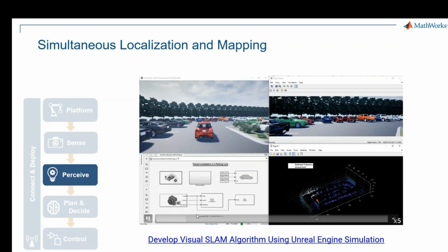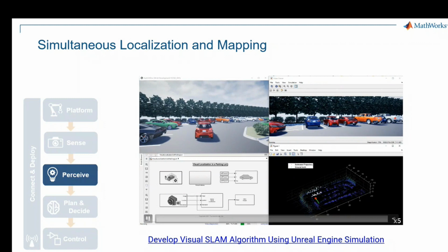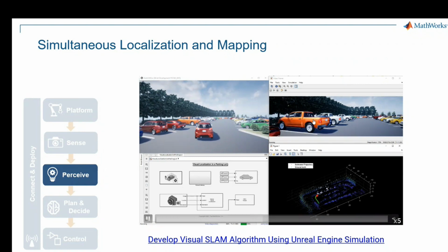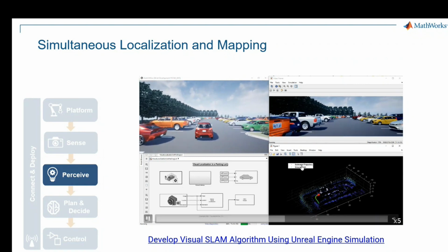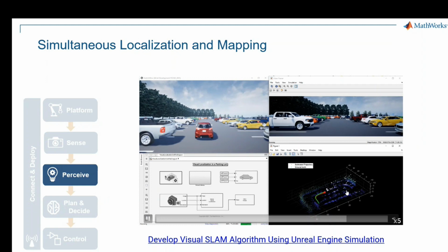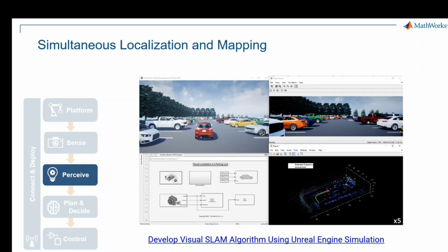And maybe it's too small to see, but the idea of this algorithm is that at each frame, it's going to detect features on it that are going to be added to this map. And these features are going to be tracked over time. The tracking of it is going to create an optimization algorithm for the localization, and also keeping them is going to create the map as you see below. And once this vehicle comes back to a position that is already known, in the SLAM algorithm, there is something called loop closure. That is an optimization algorithm that lets you close the loop and actually optimize all the drift error that was accumulated over time.